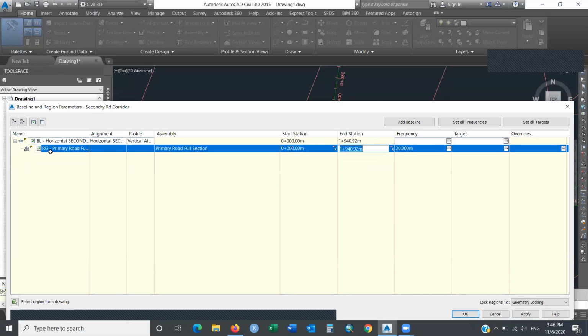It is for the RG, which is my current section, okay? So this is to 400. In your case, you need to look at the number and put the proper number here. You need to look at the station that is on the intersection and set back 100 meters. For me, it's 500. I take away 100, it's 400.